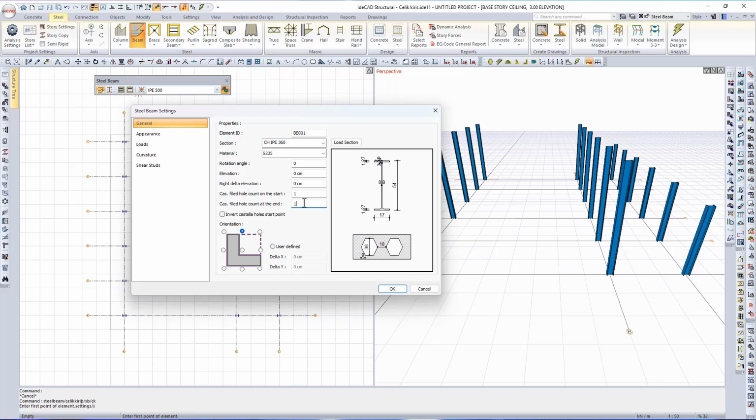This helps prevent capacity deficiencies that could arise due to the shape of the moment diagram. Even though moment-resisting connections are less common for castellated beams, if you are connecting them to columns or other primary beams using rigid joints, this adjustment becomes important depending on the structural demands.